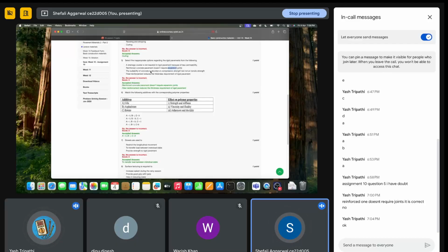So in that case, as I told you, we will provide a slit, like after a complete pavement is laid down, we will provide some slit to give it a type of expansion joint only. It won't be a full joint as we are providing in slab kind of pavements, but there will be a slit or joint. So maybe the way this statement is said is wrong, but in case of RC design, we will always provide a small joint in between after some time.